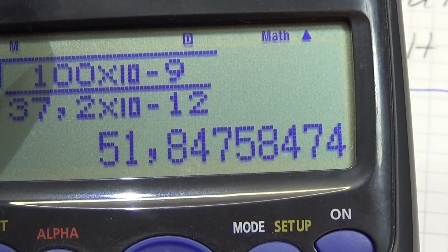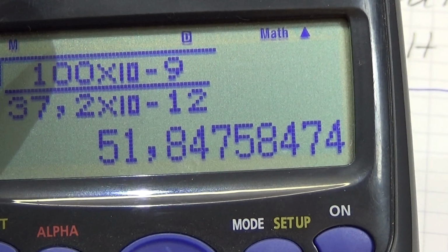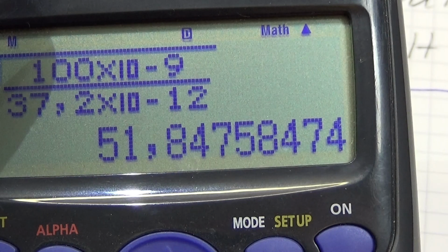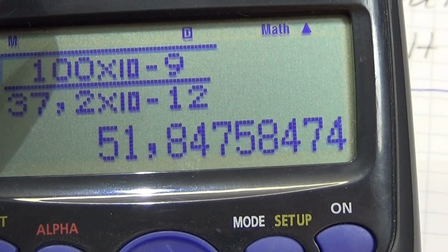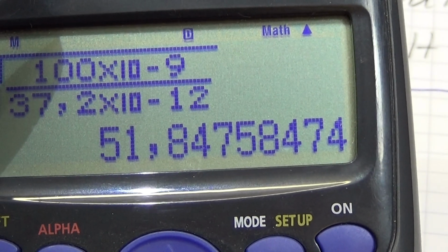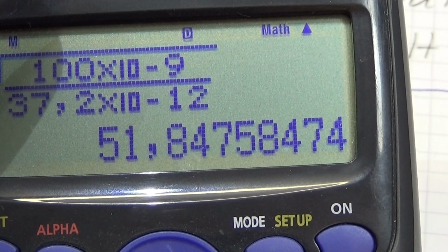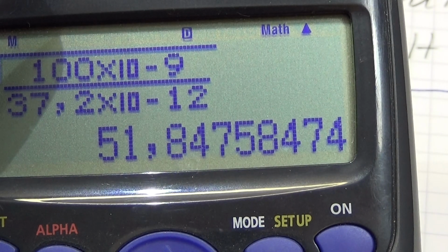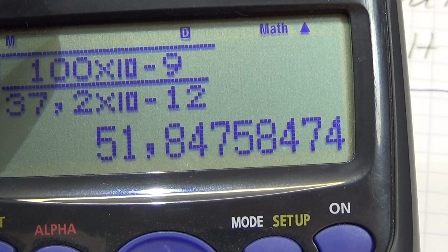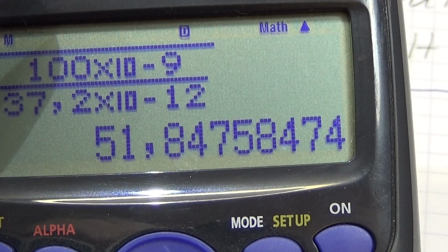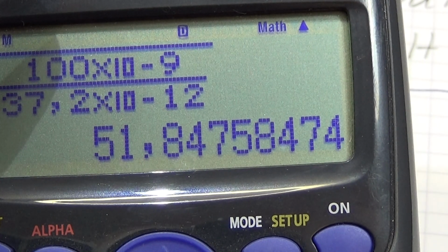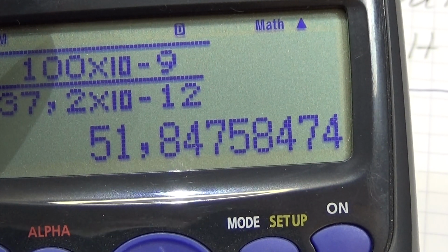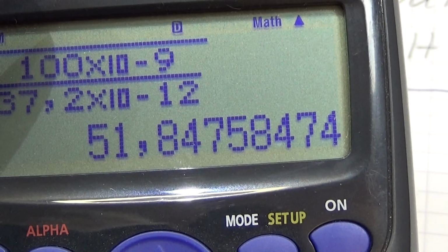We need to be able to distinguish a 75 ohm cable from a 50 ohm cable, because these two coax cables very often look absolutely similar, and 75 ohm is used in local network setups.